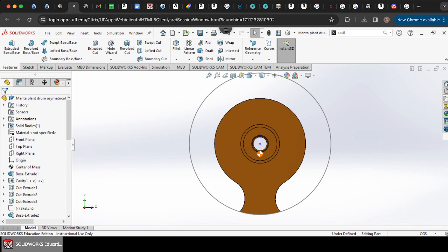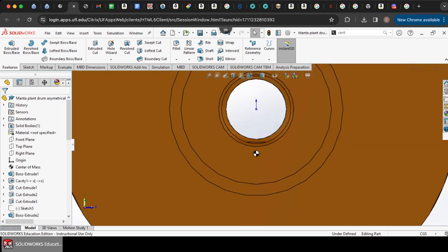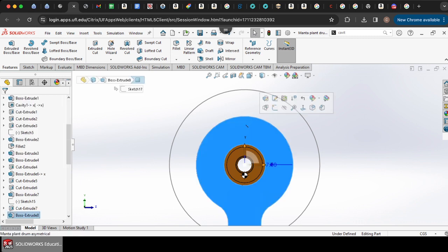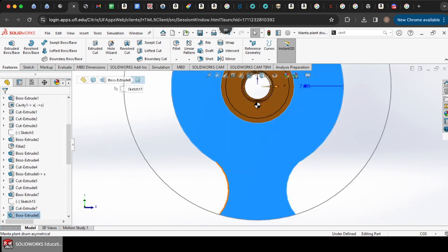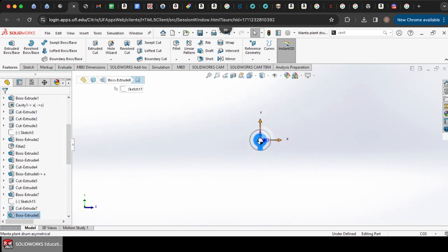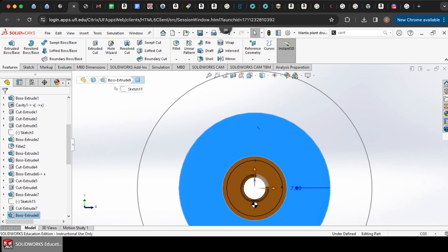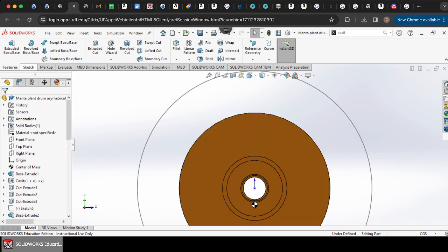With discs, it's a little more complicated because you have to find the angle that you want to make your counterweight at. For this, we don't really have to worry about that as much because we made this tooth basically straight down, and there's no other geometry to mess with it, and this is symmetrical, so we know that we want our counterweight straight up vertical on this other side here. You'll understand why that's more complicated when we get into the disc.